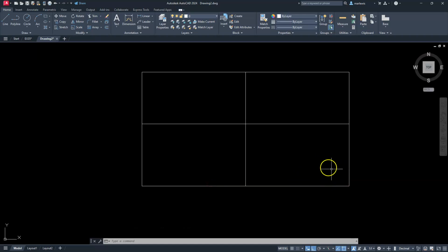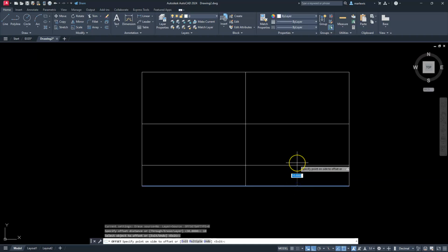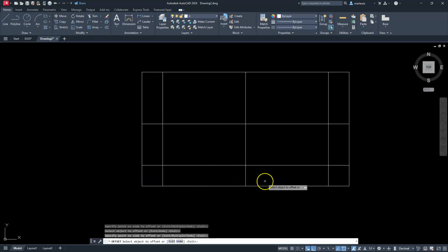Alright, so I can start here at the bottom here, and let's go ahead and start offsetting some things. So let's go ahead and offset, give it a distance of 10. That's what we're going to have here at this surface. And then we're going to do also some offsets of 10 going across here. Alright, so we do have that surface here. We're also going to have a hidden surface that's going across here. But like I said, we're not going to worry about that now or overcomplicate our drawing just yet.